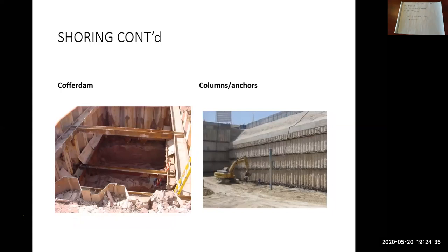So other methods of shoring, this one here, this is what my company does a lot of, the work that we do. We typically build pump stations. So pump stations are normally built right close to large water bodies, so the ocean or major rivers. They're usually quite deep in the ground. So of course, if you dig that deep, you're going to hit groundwater fairly quickly. So you need to construct a shoring system where you can have vertical walls.